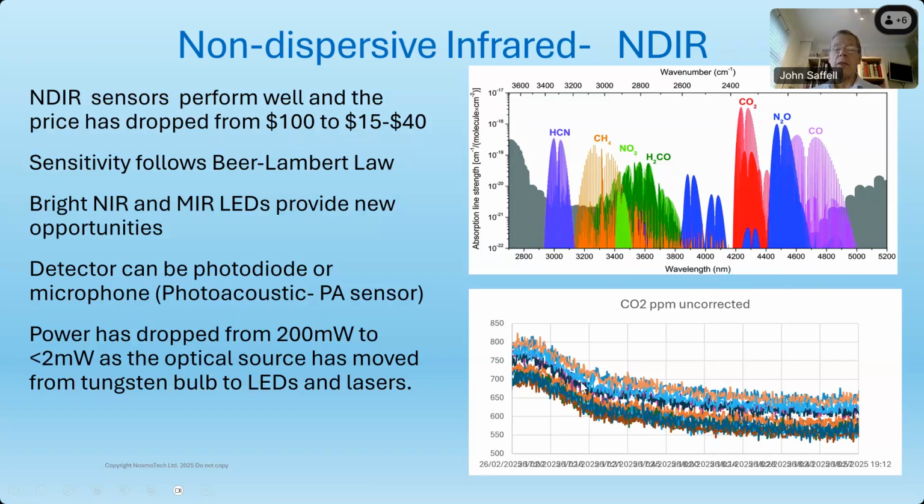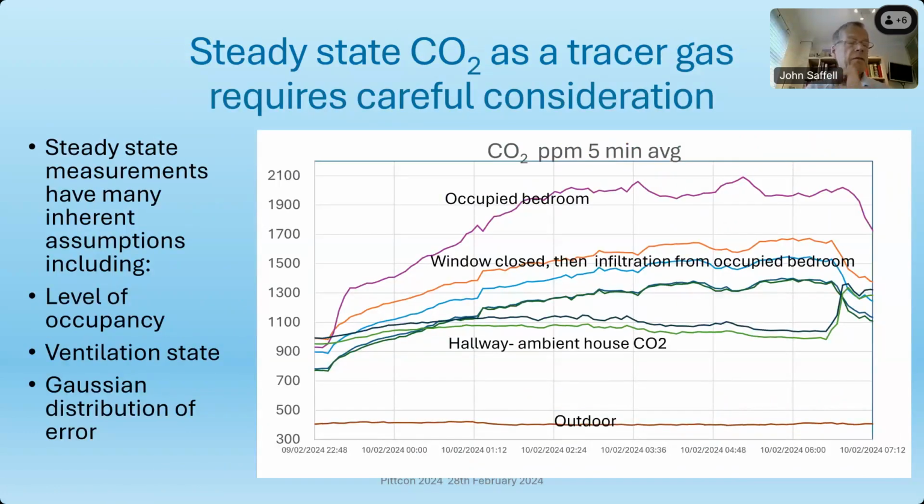And here's what you typically get with a tracer gas, and this is from 8 different sensors, all working together. And you can see they're plus or minus 50 ppm at about 700 to 800 ppm of CO2. So you can get reliable, what's called repeatable, and I believe the word is precise, but not necessarily accurate sensors. And we're just about there. We have just 1 minute over, just to show you there's a discussion about instability.